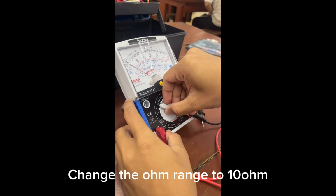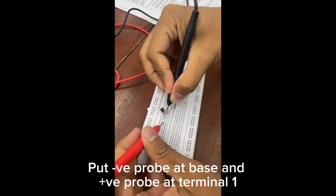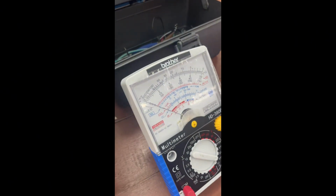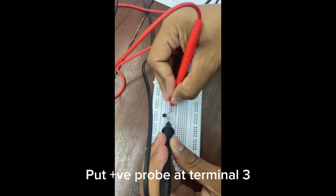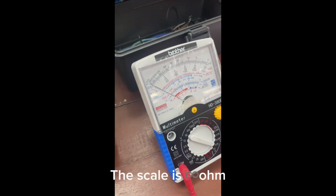First, change the ohm range to 10 ohm. Put the negative probe at the base and the positive probe at terminal 1. The scale is infinity. Then, put the positive probe at terminal 3. The scale is infinity.